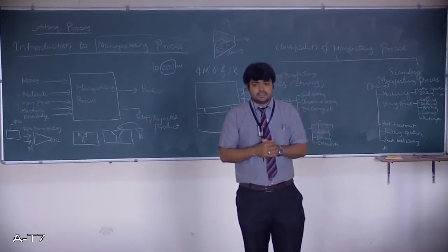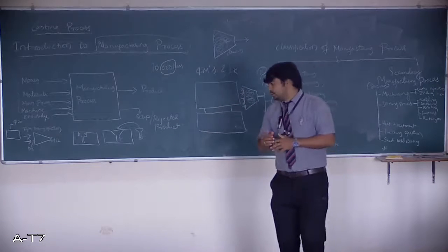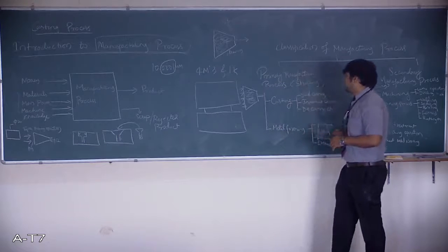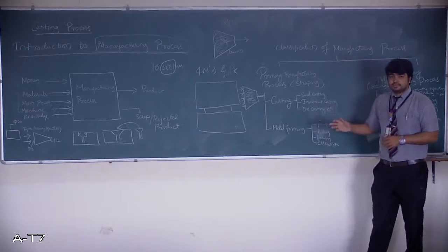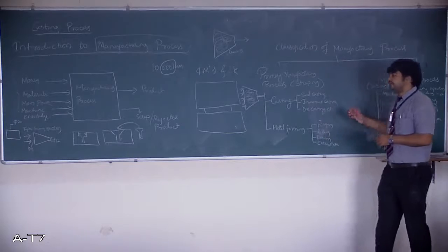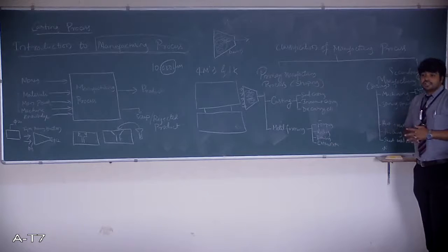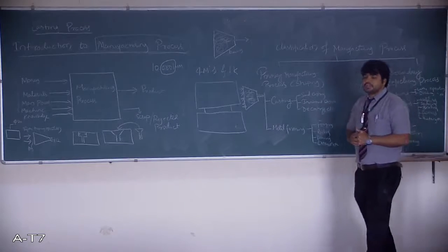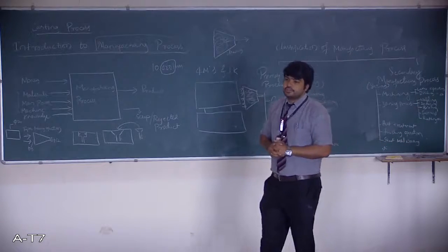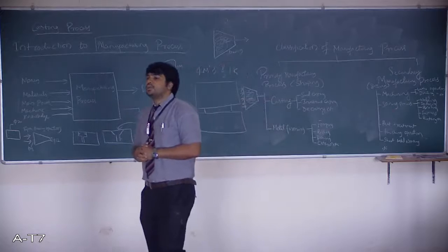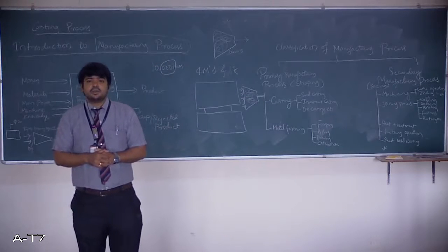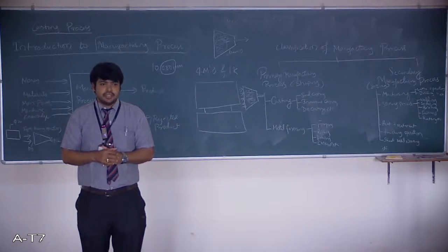In certain cases, when metal undergoes forces in metal forming, or thermal stresses in the primary manufacturing process, or even in the heat treatment process or the machining process, then the properties of those materials have to be enhanced, or the stresses that were developed in the earlier manufacturing process have to be relieved. So in those conditions we go for heat treatment. We are going to heat the materials to their recrystallization temperature, and then cool them to room temperature.